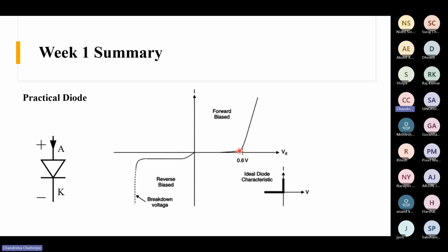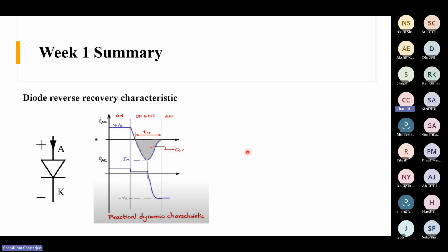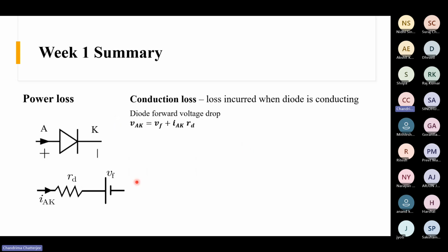If you want to represent it electrically, how will you represent it? This is a constant voltage, right? So we represent it in terms of a constant DC source. This is what we call VF. You can denote it as VT also, or the knee voltage, anyway. So this is that voltage. And this RD is the resistance of the diode, right? If you are expressing it as the piecewise linear model, it will be a constant resistance. But